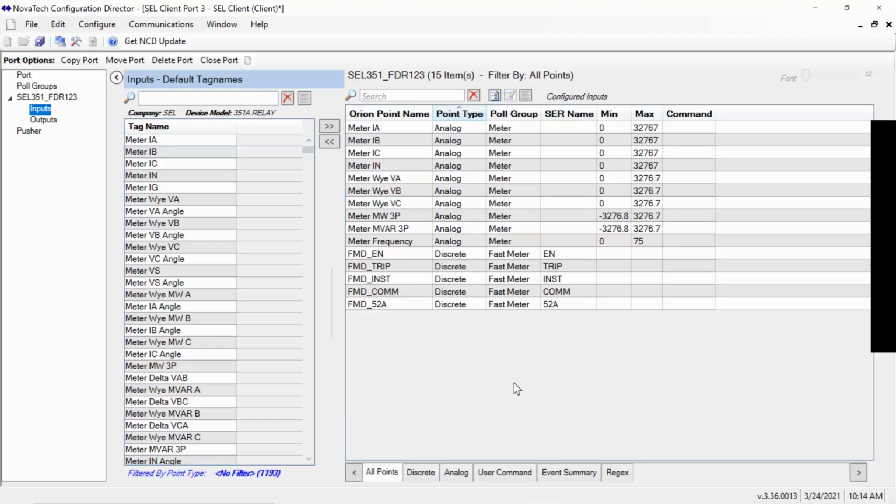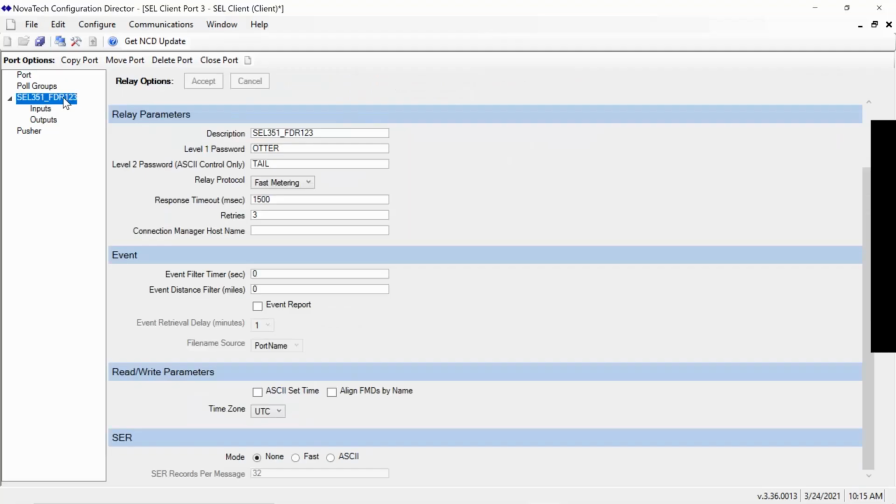The only thing that's really going to vary between your multiple feeders from a communications perspective is the name and then potentially some of the addressing from one relay to the next, perhaps usernames and passwords, etc., on the Schweitzer protocol. But again, all of these points and their parameters are going to stay the same from one device to the next. So what I can do in here, if I had a 485 string and such, is I could actually duplicate the device internally.